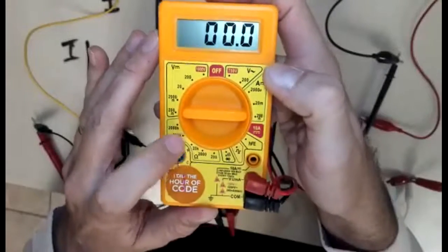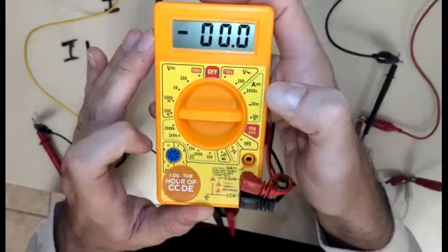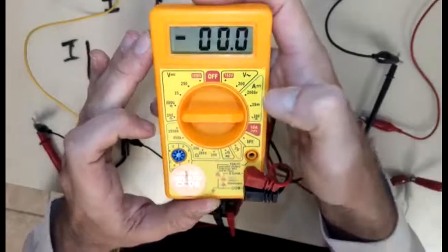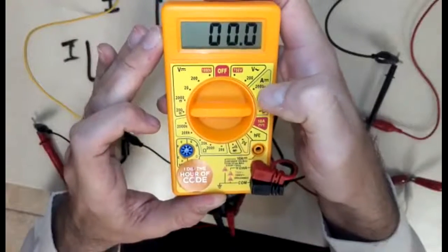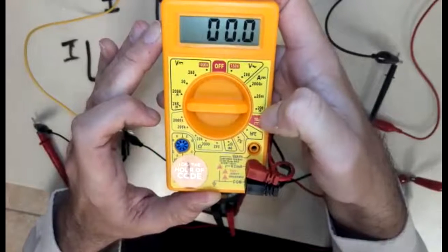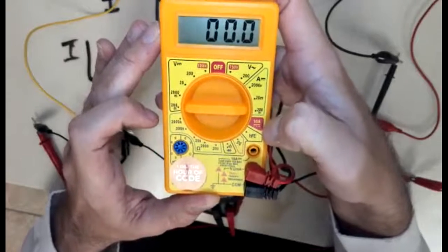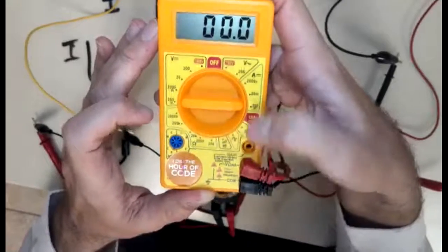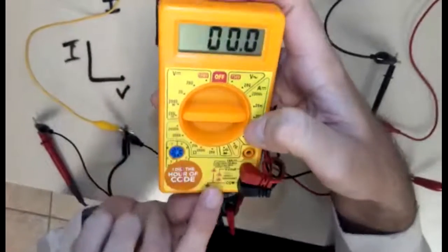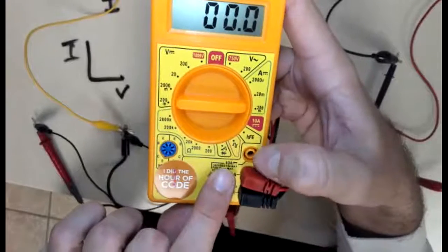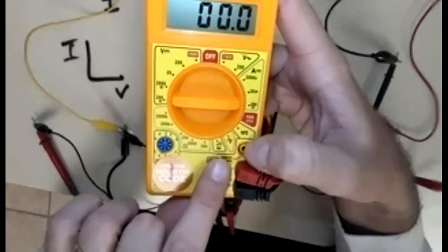So it's a voltmeter, it's an ohmmeter, it's an ammeter. It's a multimeter. Measures all those things. These different values are the range. So it can measure up to 2000 microamps, up to 20 milliamps, or up to 200 milliamps. I've got it set to 200 milliamps. In order to get to this 10 amp range, I need to disconnect this red lead and plug it in here. You see how down here it says 10 amp max. That's a special port just for high currents, like 10 amps.